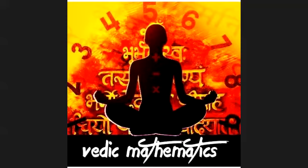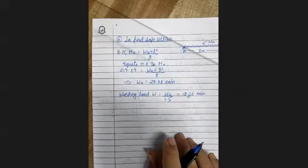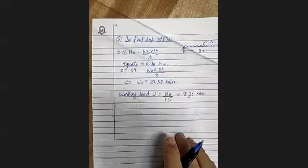18.25. 18.25. So now we got the working load also. So now you can find out the safe UDL. So safe UDL is nothing but the working load minus the self weight of the beam. If you subtract, then you will get the safe UDL.